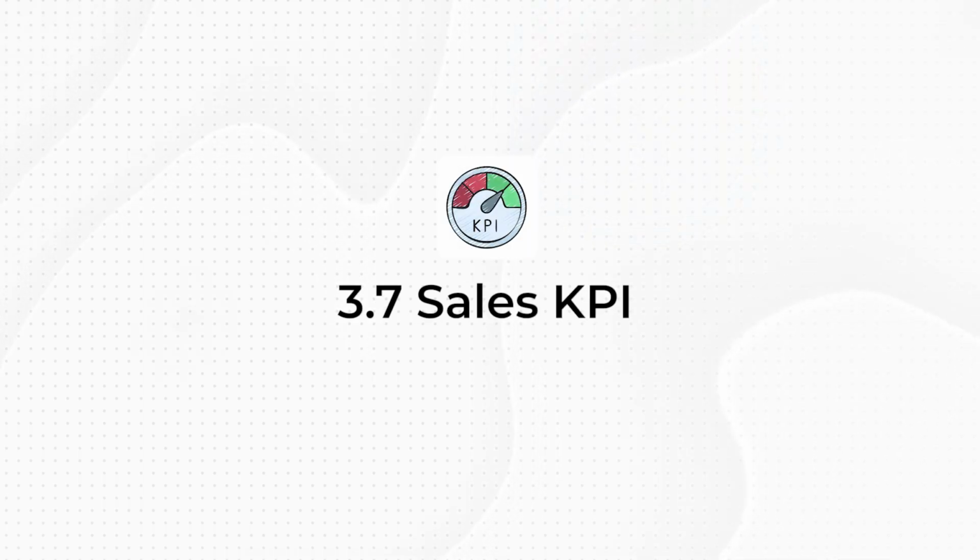One last thing that I would like to do that lifts up the quality of the entire dashboard is by adding KPIs to my dashboard. What are KPIs? KPIs are key performance indicators. Those are like signs that give you red, yellow, or green, that things are working fine or not. These KPIs are inherently available only in Power Pivot unless you want to create these KPIs using formulas in Excel. But please take a look.